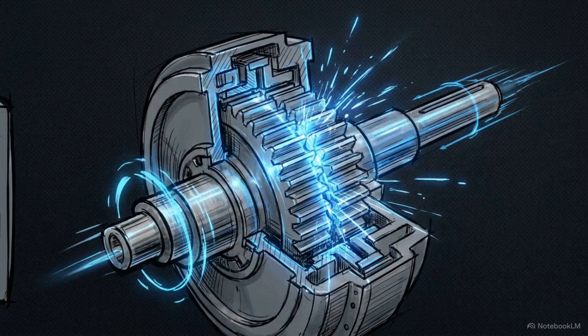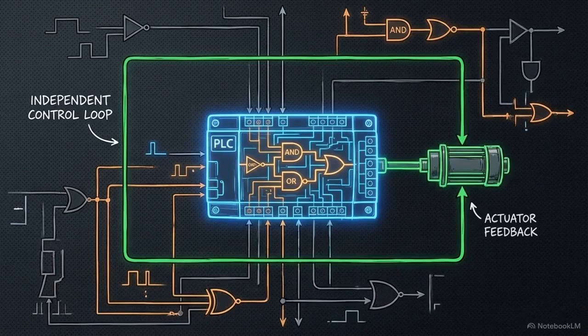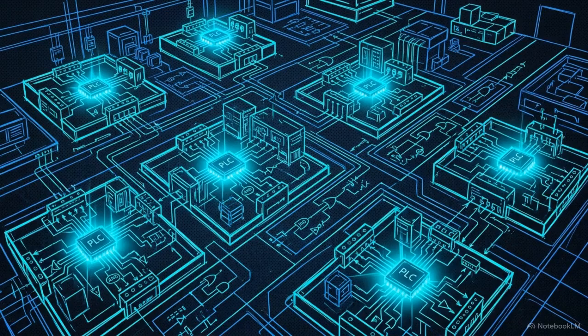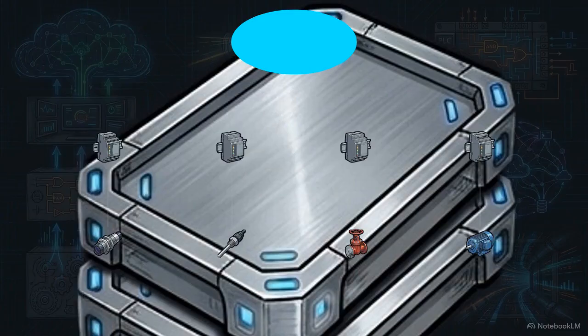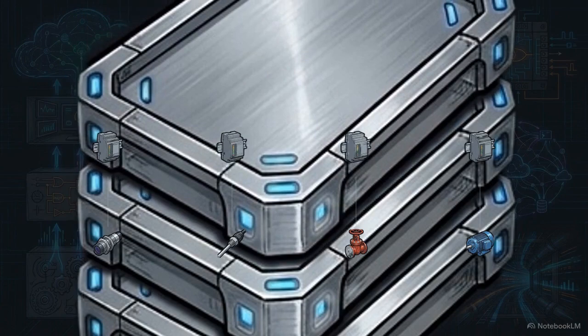The critical feature of this loop is speed. PLC control happens in real time, frequently executing these logical equations in a matter of microseconds. The PLC does not need to ask for permission from higher levels to execute these immediate safety and operational functions. By managing this logic locally, PLCs grant the factory floor the autonomy to operate massive machinery safely and continuously in real time.